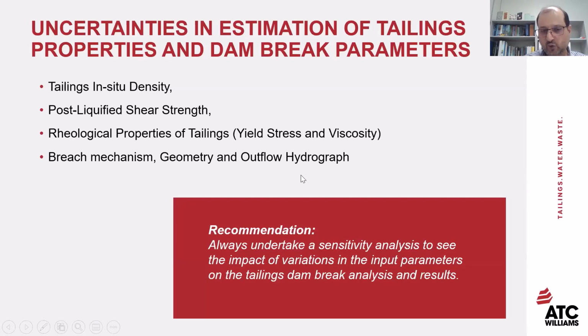It's recommended to always undertake a sensitivity analysis to see the impact of variation in these input parameters on the tailings dam break analysis and the result. Without this sensitivity analysis, a dam break study would not be complete and it would be questionable. So the parameter may not have a significant effect depending on the project, depending on the geometry, or may have a significant impact.